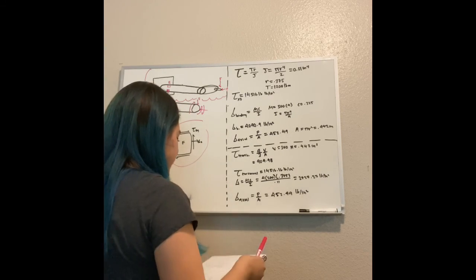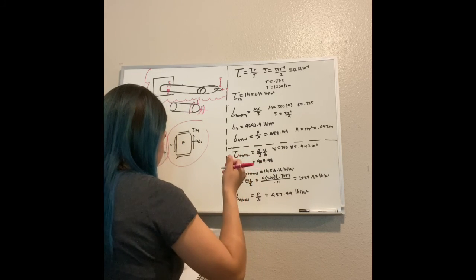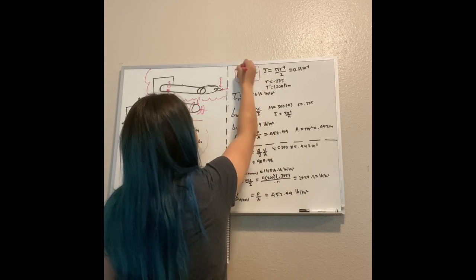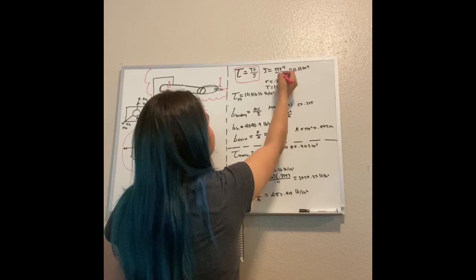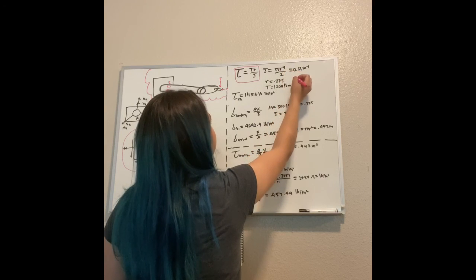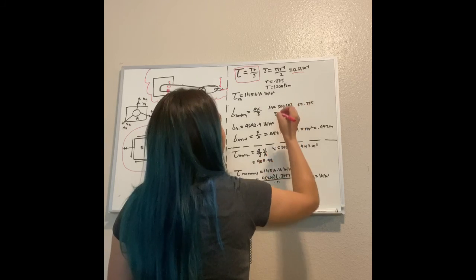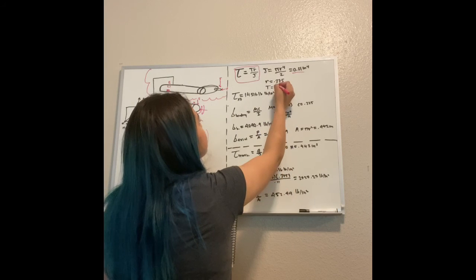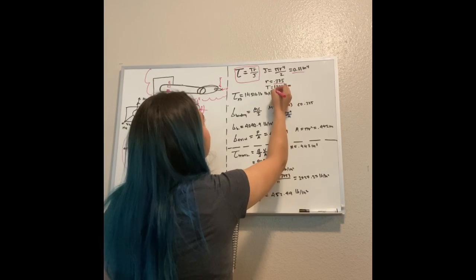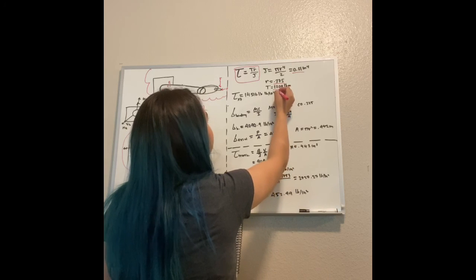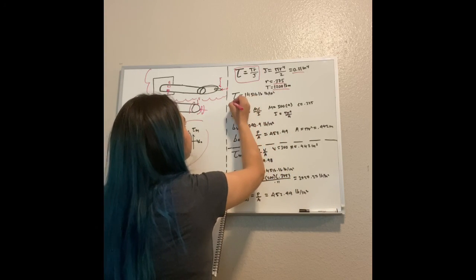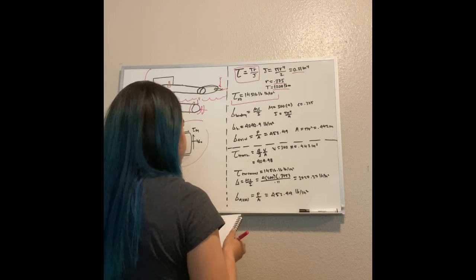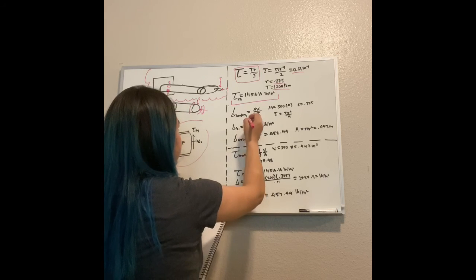In the stress components of E, we have a torsional and a bending. We're just going to go over them real quick. Here's our torsional stress. Solving for J, which equals pi r to the 4th over 2, in our case gives us 0.31. The R, which is given in the problem, is 0.375, and the force that we solved for is going to be 1200. In all, that gives us an answer of 14,516.16.